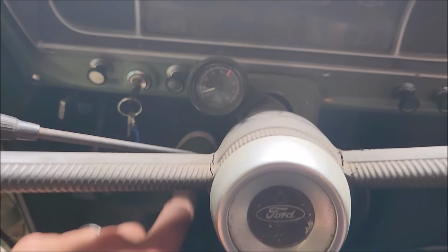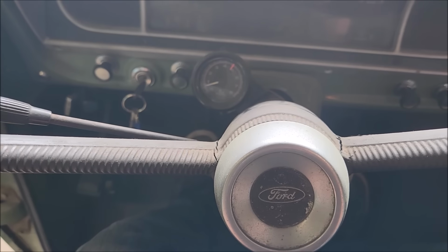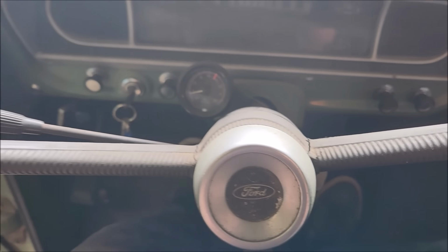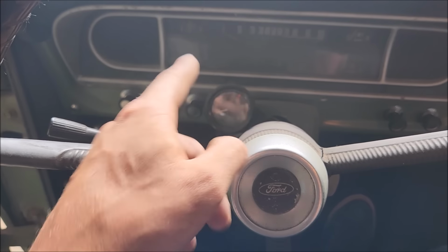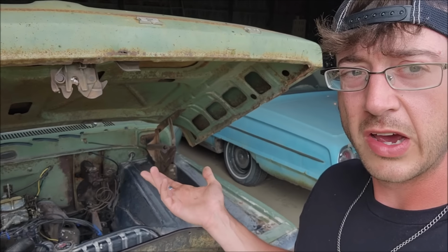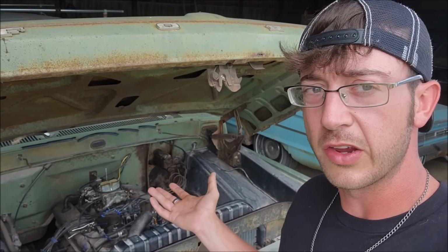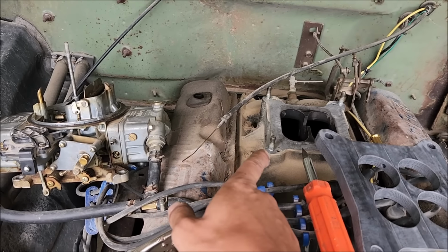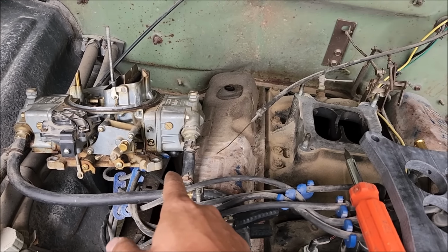Fires right up. This is the slowest responding tach I've ever seen. You can tell with the exhaust note and the tach, they're totally not in sequence. So anyway, now it's just going to run, idle, and the carburetor is going to run out of fuel, and then it's not this horrific mess when you go to pull it off. Real easy. All right, we got the carburetor off and just simply cantilevered out of the way.